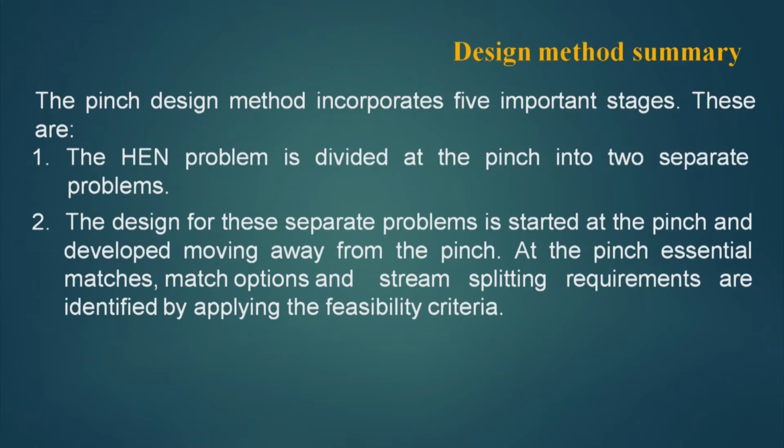The design of these separate problems is started at the pinch and developed moving away from the pinch. This we have explained in detail. At the pinch, essential matches, match options and stream splitting requirements are identified by applying the feasibility criteria. The pinch gives some feasibility criteria based on which the matches can be put. They are different for hot end and they are different for cold end. Then whether to go for a splitting of a hot stream or a cold stream is also covered by some rules and regulations.